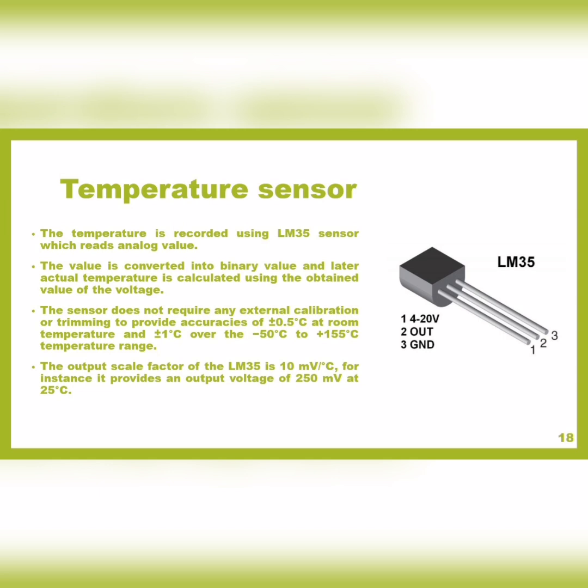The output scale factor of the LM35 is 10 millivolts per degree Celsius. For instance, it provides an output voltage of 250 millivolts at 25 degrees Celsius. The figure beside it represents the temperature sensor.